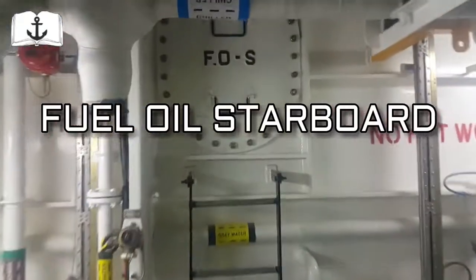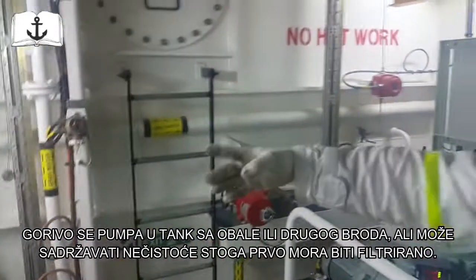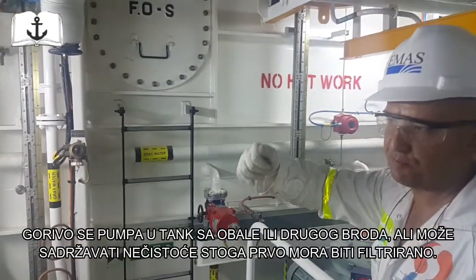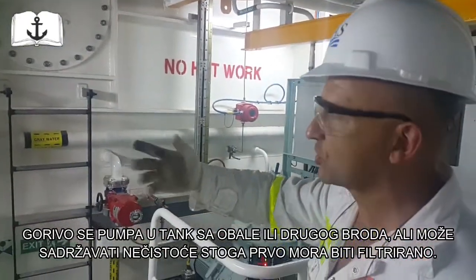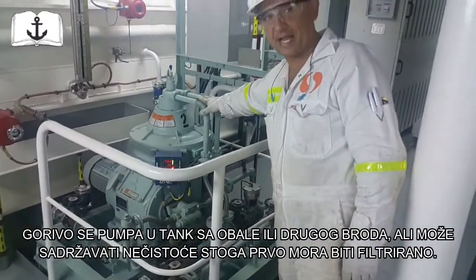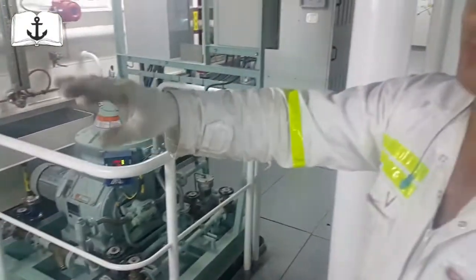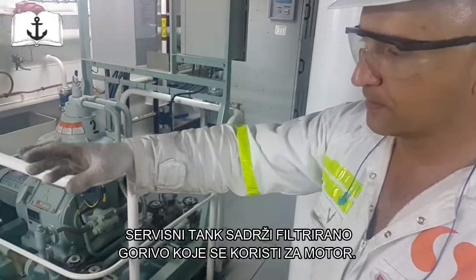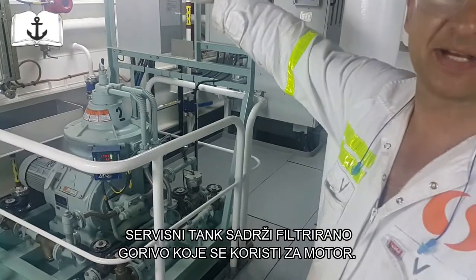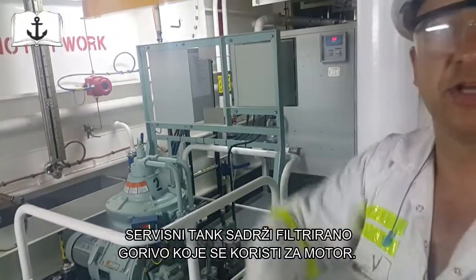And basically on every rig or ship it's done like this: you have the storage tanks where you keep the spare fuel when you get it from the ship or on the hose or whatever. And then you have this one, it's a purifier of the fuel. The fuel is not maybe dirty, but you don't know the condition, so it's purified to the day tank or service tank. And then from the service tank it's going to the engine.